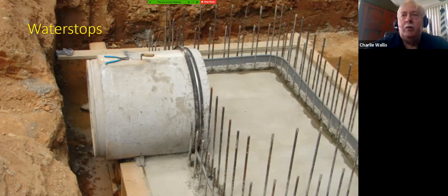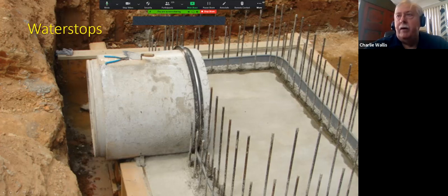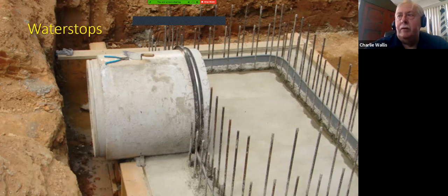And spillways need to be watertight structures. Here's a riser that is being constructed and the base has been poured. We have the initial reinforcing steel sticking out. It was embedded in the initial pour. It sticks out, and half of this water stop was also embedded in the concrete in the base. The walls will be formed on top of this, and then when that concrete is placed, this will provide a nice impervious barrier in the joint so that water can't leave it. And notice that this water stop also goes around the spillway pipe.